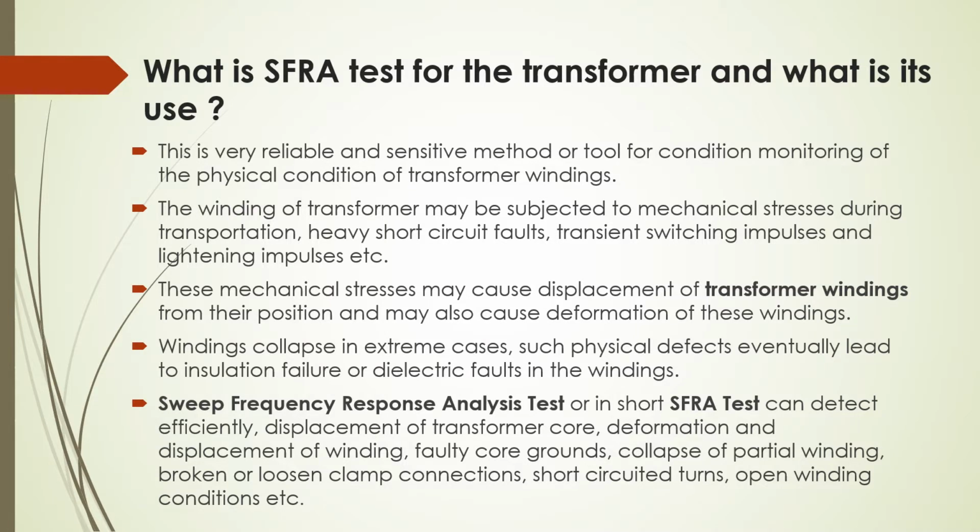What is SFRA test for transformer and what is use of it? This is a very reliable and sensitive method or tool for condition monitoring of physical condition of transformer windings. The winding of transformer may be subjected to mechanical stresses during transportation, heavy short circuit faults, transient switching impulses and lightning impulses, etc. These mechanical stresses may cause displacement of transformer windings from their position and may also cause deformation